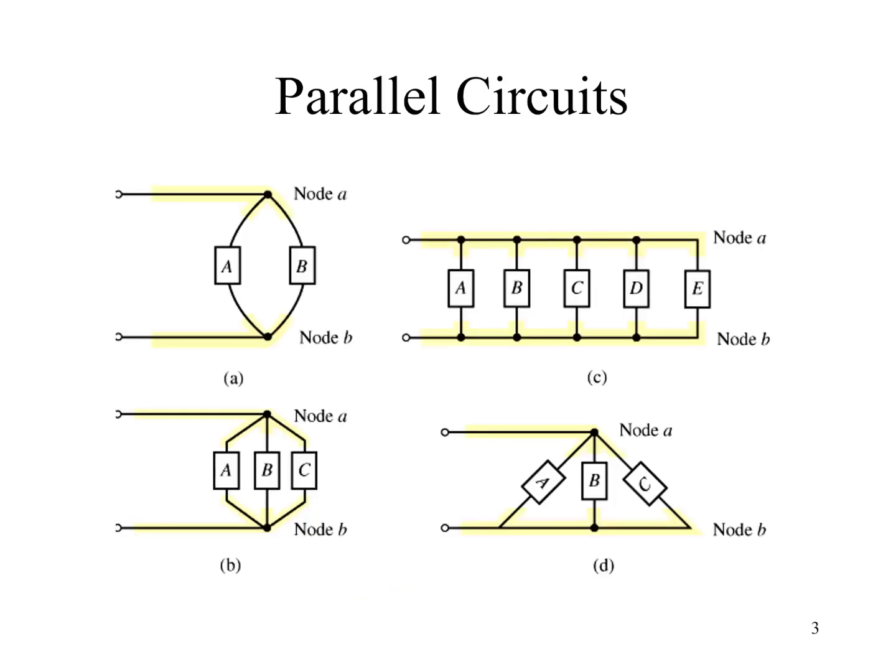So it doesn't matter how circuits are drawn, the way we evaluate their connection is by following the nodes or the connections that make up the circuit. And so don't be fooled when you see examples, both from the textbook and other drawings, that maybe don't look traditionally like a parallel circuit.